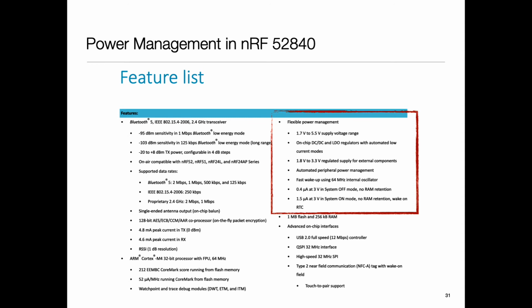Some processors have native support for DVFS. Other processors rely on the board providing an adaptive power supply in order to be able to do it. So here you would see that Nordic gives a whole bunch of power management features, a range of power voltage. I'm just reading: on-chip regulator, so it has on-chip capability for voltage regulators, which it can adjust.